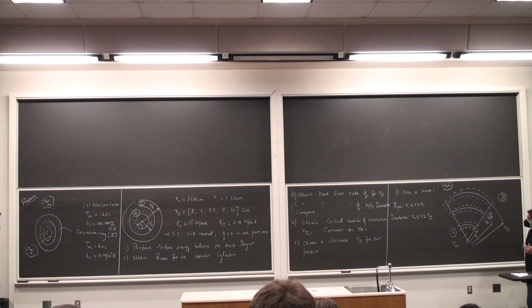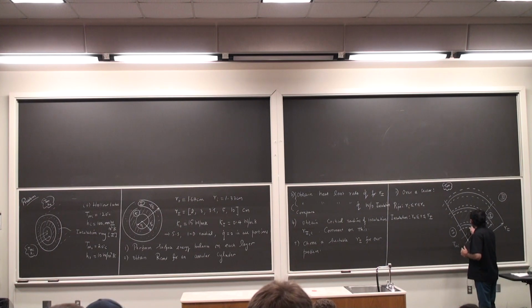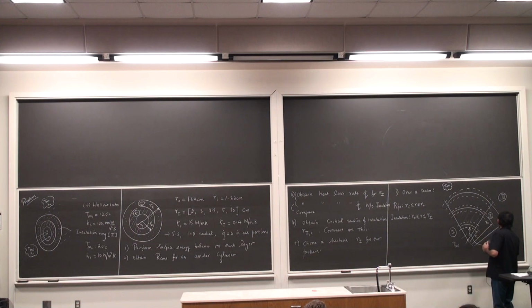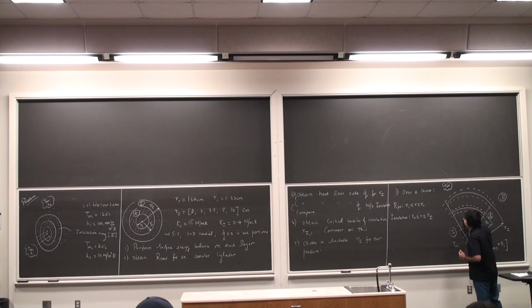I'm going to have convection first. This is Q double prime convection I multiplied by the area. Okay, then this is going to go as conduction into the first ring here. So this is going to be Q double prime conduction I, okay, multiplied by the area AI.